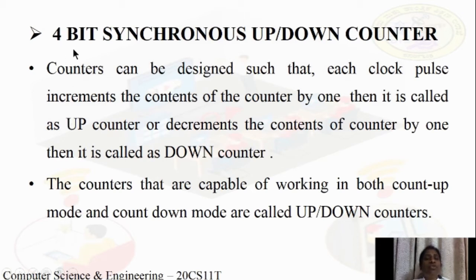In this 4-bit synchronous counter, we should give the clock to all the flip-flops simultaneously. It should be designed in such a way that the contents of the counter are incremented by 1 for every clock pulse.